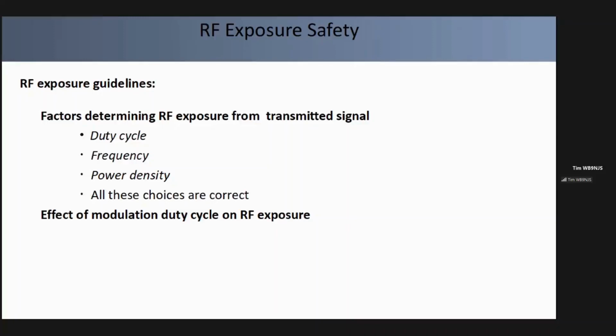What is the effect of modulation duty cycle on RF exposure? Well, the correct answer to the question is lower duty cycles permit greater transmit power levels. So what's a lower duty cycle modulation?